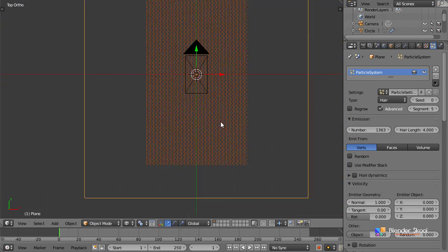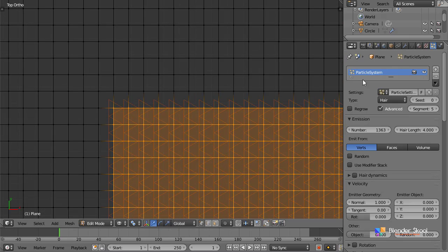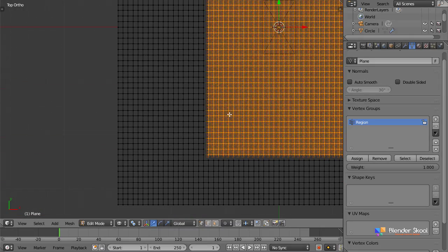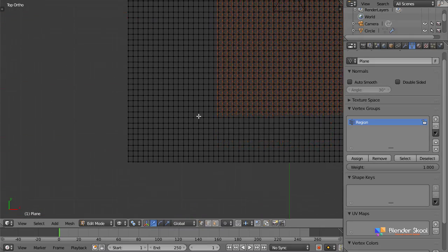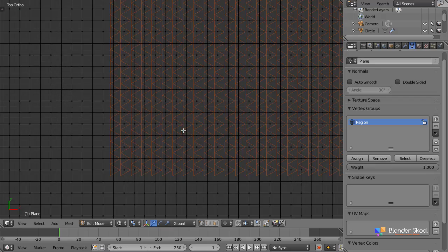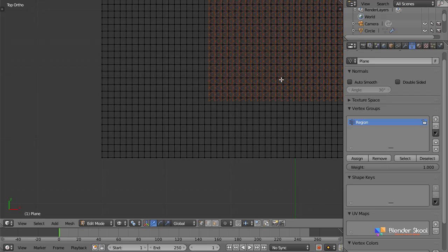And also now what we need to do is distort the orientation of all these particles. If you have seen my abstract hexagon tutorial, you would have seen that I had edited the plane a little bit so that we have this nice interlocking between the particles. So we're going to do the same thing over here as well. So again, in the vertex groups, add in a new vertex group, and we're going to name it, let's name it alternate.